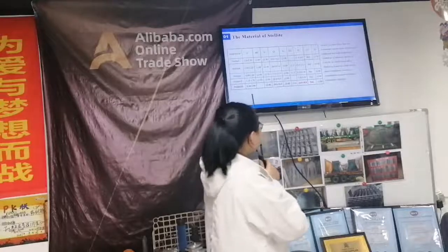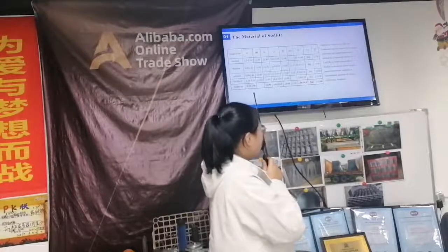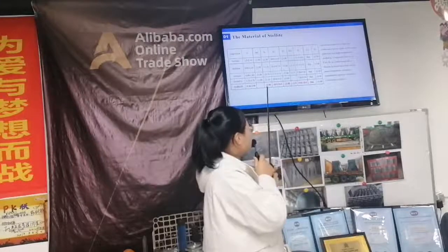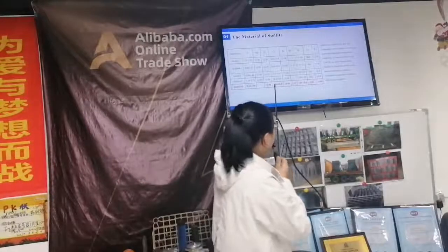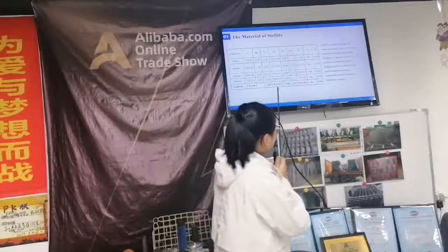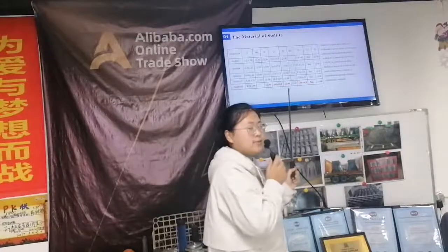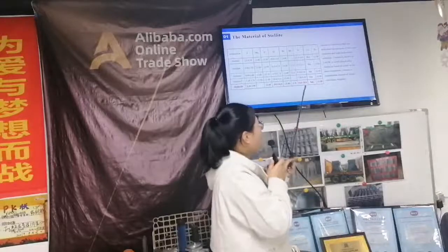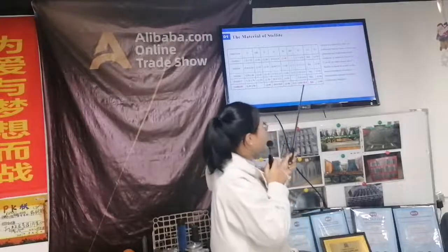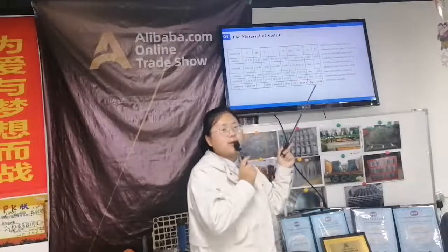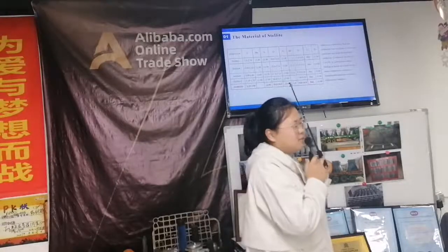620. For carbon is 2.2 to 3.0%. For silicon is less than 2.0%. For chromium is 30 to 34%. For nickel is less than 3.0%. For tungsten is 14 to 18%. For iron is 3.0%, and the cobalt is balanced.